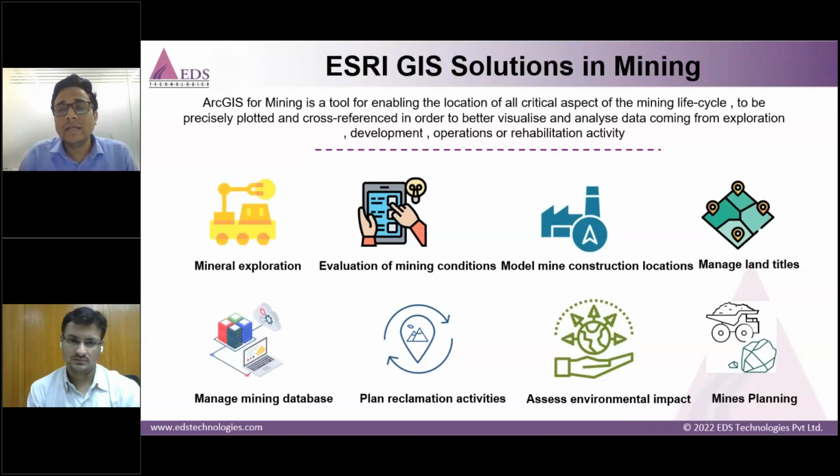In mining conditions, like when we are doing a drone survey for a mining area and we create a 3D model of the mining area, we will see some examples of it. Once the 3D model and elevation model are created, we can identify if blasting is happening in a certain part of the mine, how much material is going to be extracted, if any haul roads are created, whether the slope of the haul road is within permissible limits or not, and whether driving vehicles on those roads is safe or not. This kind of assessment and evaluation we can do.